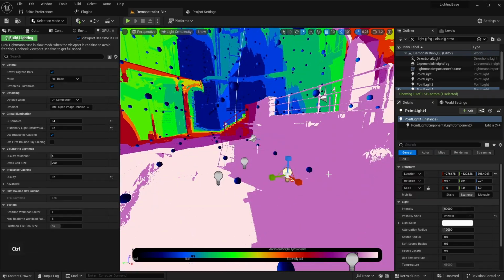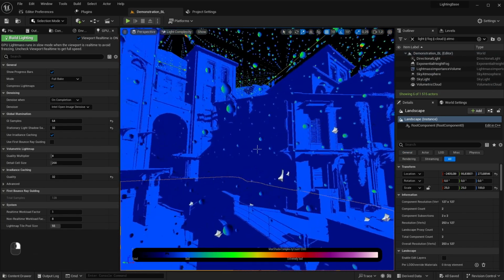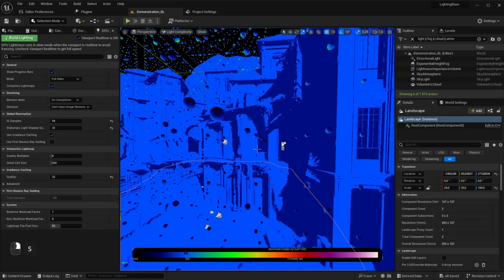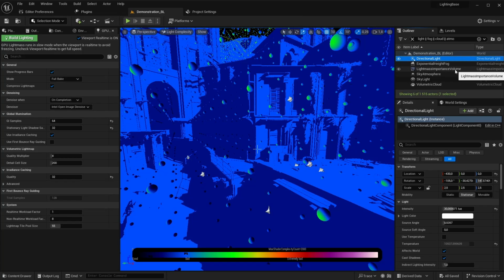Right now, I will get rid of the lights that I had to the exterior here and add just a few of the lights inside the interior. But before that, let me actually do one change because the light units inside Unreal Engine are mostly physically based. Let me actually go back to the directional light or the sun and change the intensity of this quite high.